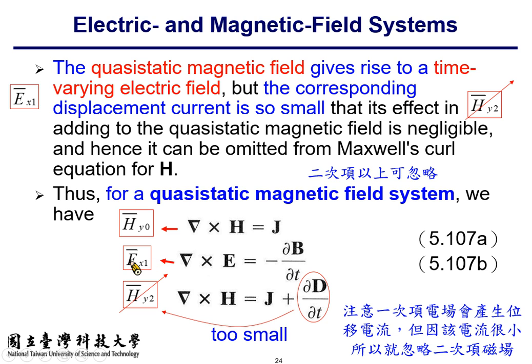So you have the E sub 1 term. Then, of course, the time varying electrical field should provide higher order magnetic field terms as suggested with this equation. However, because the electrical field produced in this structure is relatively small, we can ignore the second order magnetic field term, which means we are in the valid region of quasi-static approximation.